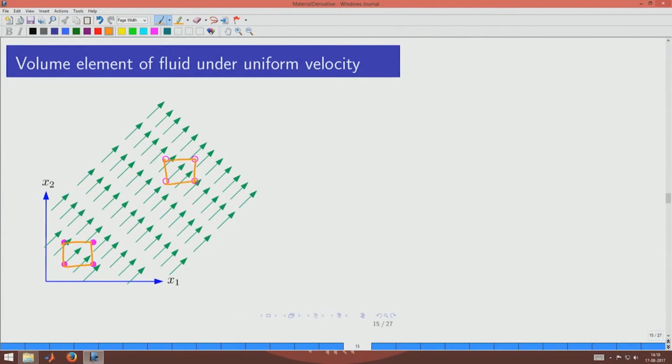then the shape of the control volume will not change. So, you can see that the horizontal distance and vertical distance should be the same for every point. So, for every point the shifts are the same in all directions because the velocity is uniform. Now, this means that uniform velocities, constant velocities do not change the control volume shape as it is moving,